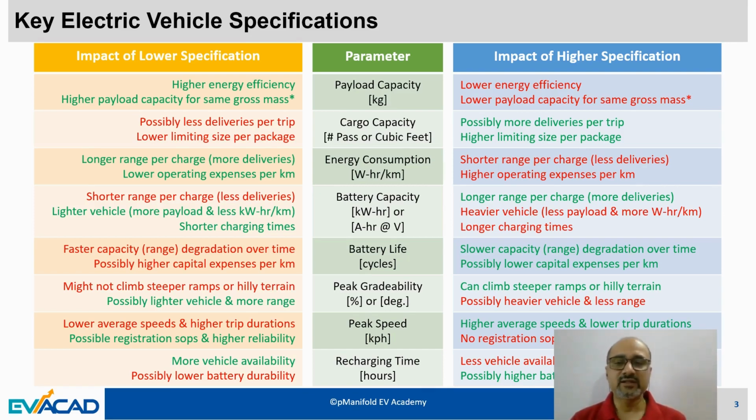Particularly in electric vehicles, you tend to have lower max speed because you do not provide multi-speed transmissions. You do not require 4 or 5 speeds; with a single speed transmission you do away with shifting, and because the motor provides a limited range of speeds, you end up with a lower max vehicle speed than the counterpart. We'll look at some sample specification comparisons soon.